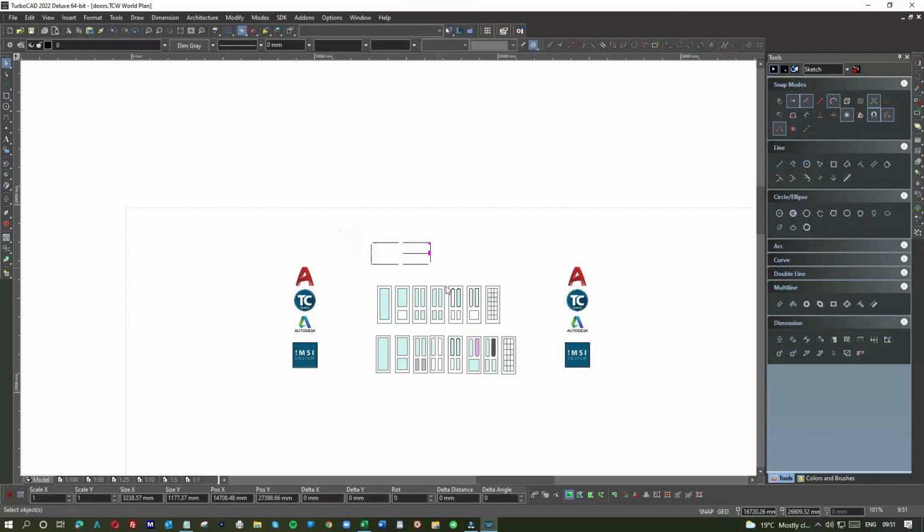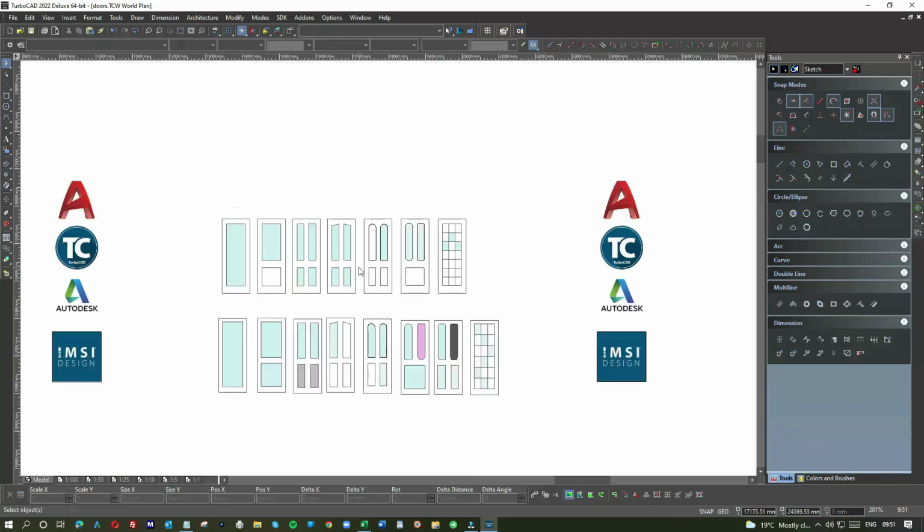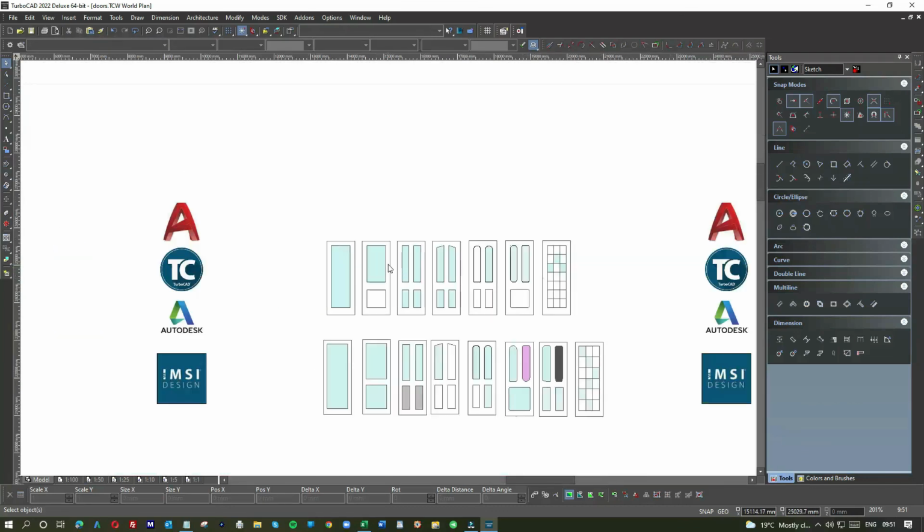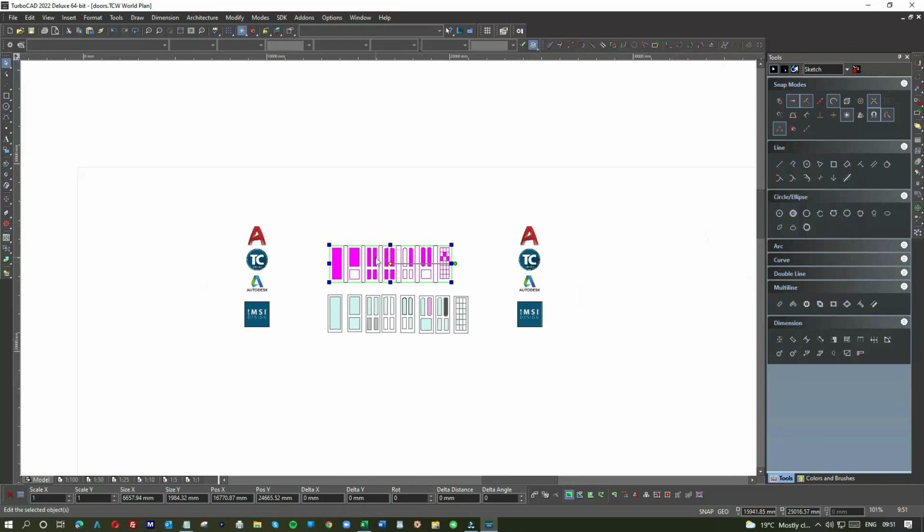The most standard kind of UK doors, and as I say, create a library if you can, and that would be a real time saver for every drawing. And we use what I call a loaded template, which means if I know I'm doing layouts, I open up a template where it's got the likes of this on the side. It's got a whole range of things.